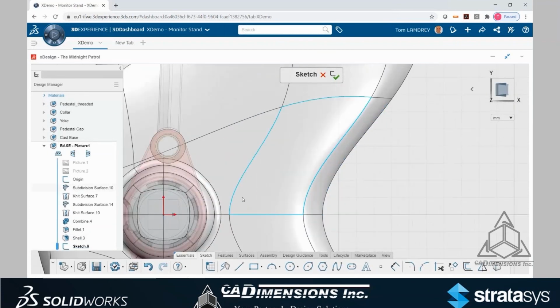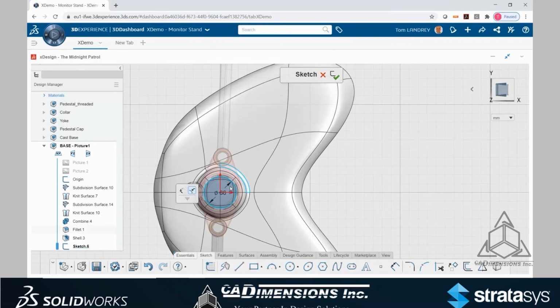Now, Kevin, I don't know if you noticed this. We worked a little different on this. I drew a circle just to cut the hole through. And when I placed it, I just clicked off, hit escape, got out of circle. And when I highlighted the circle, all I had to do was click on that little arrow and I could get right to the number. Just a different way to do it. We saw the 36 dimension from before, so let's just pop this hole through.